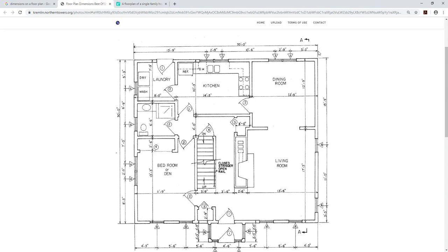Like this first string will show interior elements at the exterior wall, okay? Or openings or change in plane. And the second or third string of dimension will show the overall dimension of the project, okay? You'll see interior dimensions, so from the outside of that wall to the center line of this wall, from the center line of this wall to the center line of that wall, okay?